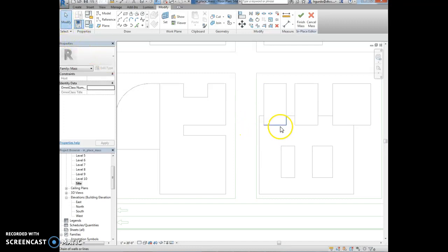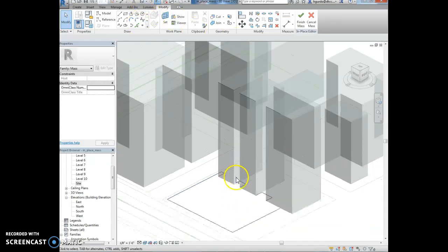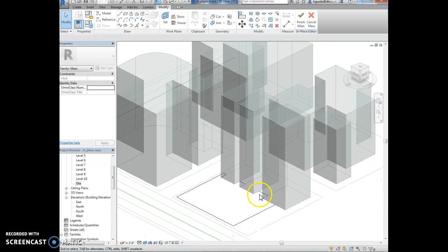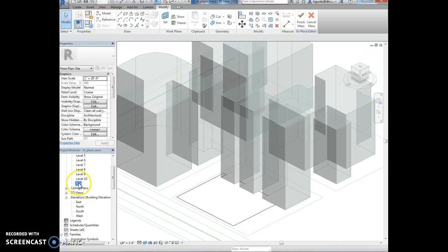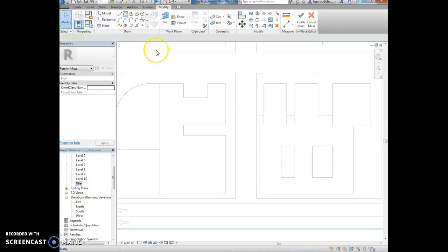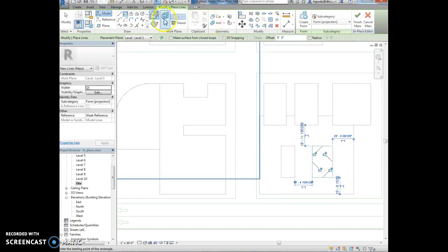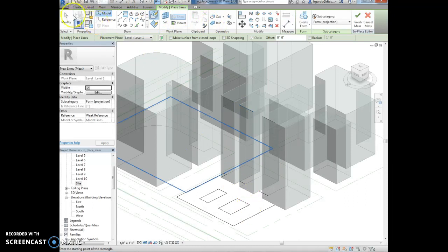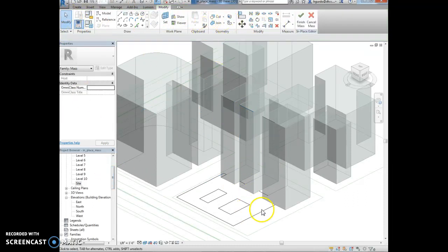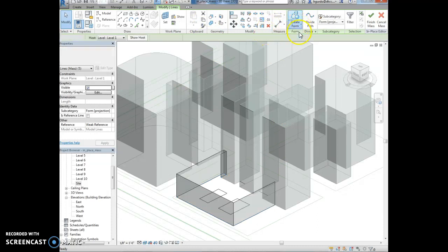Okay. And now I should have a completed shape. I hope. It looks like it. You can look at it in 3D to see for sure. Okay, it appears I have a completed shape. I also want to select the rectangles on the inside. I'm just going to use the rectangle tool. Go back to 3D. And I'm going to click on this outline, create a form.